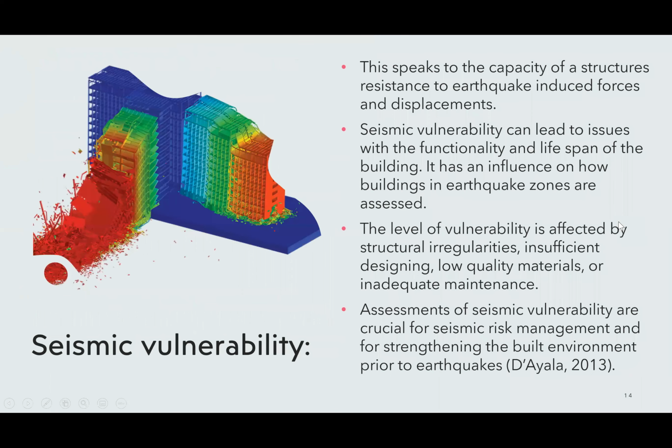Seismic vulnerability. This speaks to the capacity of a structure's resistance to earthquake-induced forces and displacements. Seismic vulnerability can lead to issues with the functionality and lifespan of the building. It has an influence on how buildings in earthquake zones are assessed. The level of vulnerability is affected by structural irregularities, insufficient designing, low quality materials, or inadequate maintenance. Assessments of seismic vulnerability are crucial for seismic risk management and for strengthening the built environment prior to earthquakes.